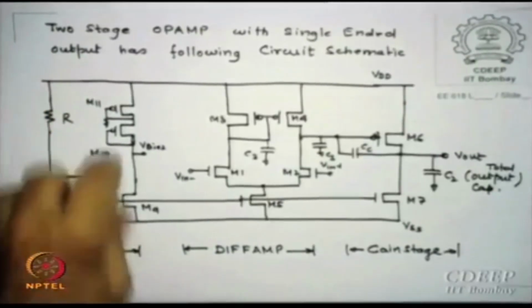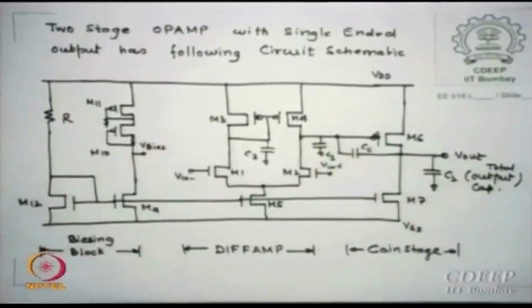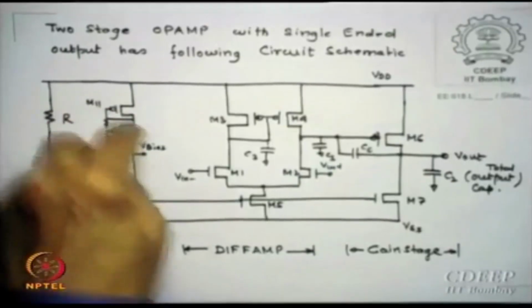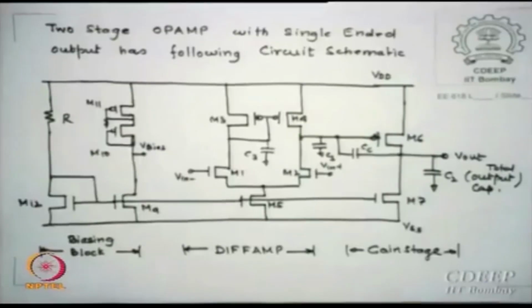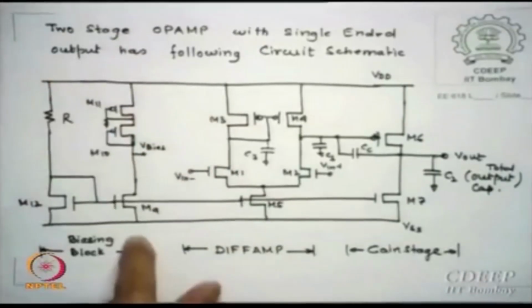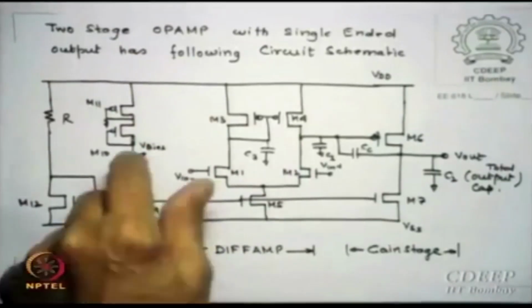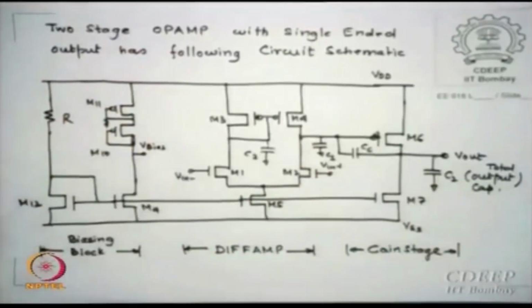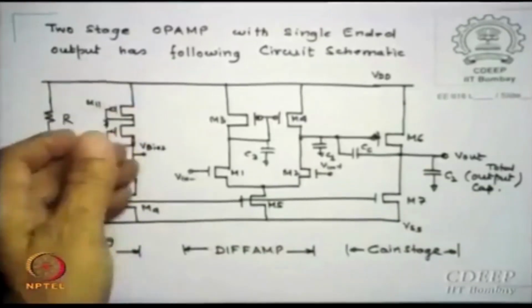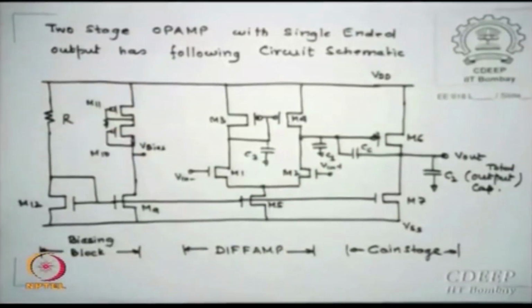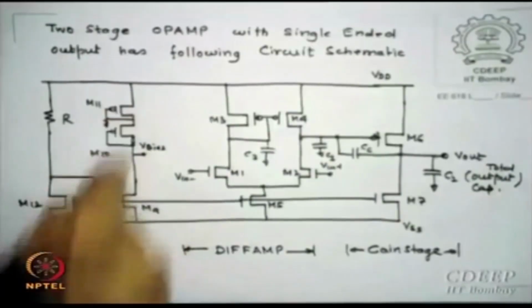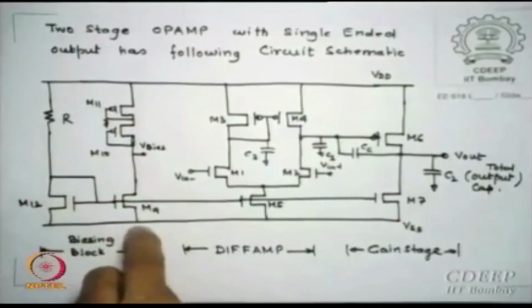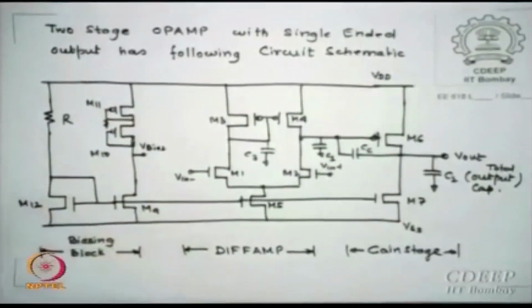Now many times you need voltages. Let us say you want to bias with VB. So I put 2 diodes, each will have some voltage drop. So VDD minus that, and at this current, whatever W by L you choose, I can decide what drop it has. So I can create a V bias of my choice. I may put even 3. But to know all that W by L for them, I need current, and current comes from M4, okay, or M9, sorry.